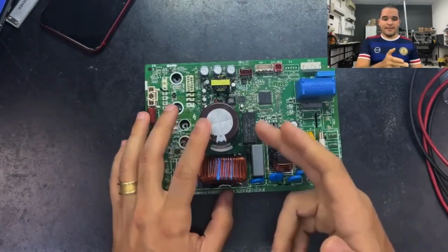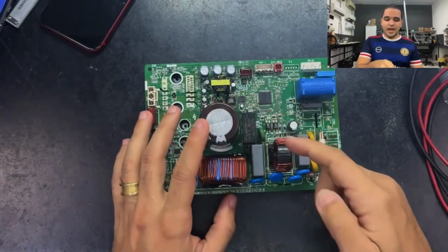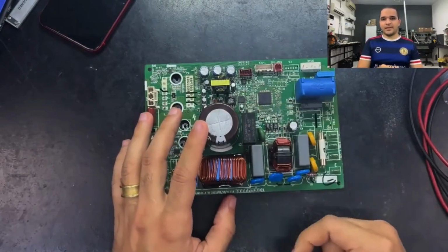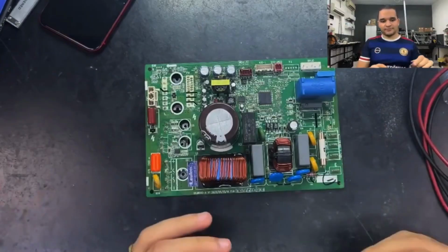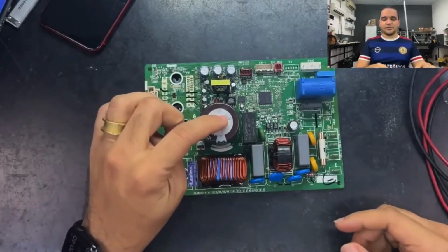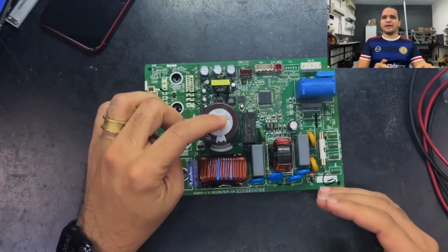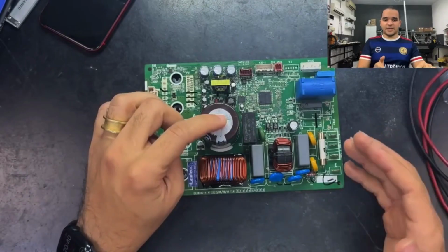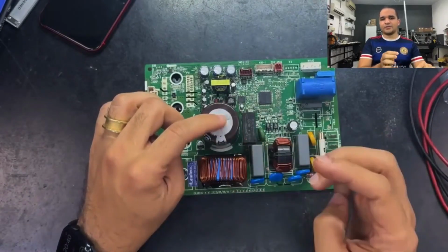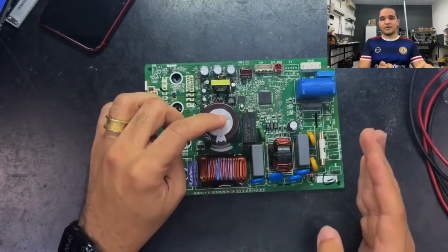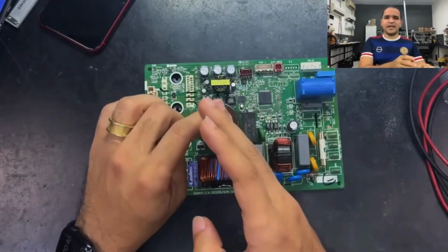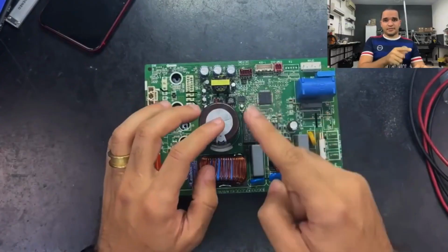Why? The sample is made using a voltage divider. It uses a series of resistors to lower the voltage to a level the microcontroller can read. For instance, let's say it cuts the voltage, so when there are 310 volts, it reads 3.1 volts. Let's assume it is divided by a factor of 100, correct? This will reduce the voltage until it transforms into a sample that is precisely 100 times smaller. Yes. 310, 310. That's it.